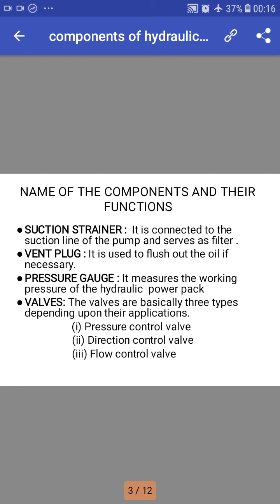The vent plug. The vent plug is used to vacuum the reservoir. It is used to flush out the oil if necessary. During the washing time of the reservoir, it is necessary.